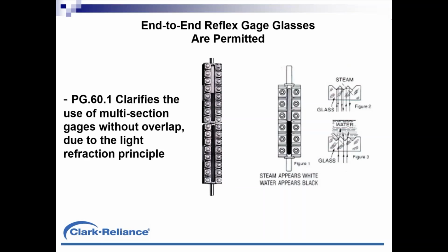So here off to the right, you can see those prisms that are molded on the inner side of the glass. So very critical, if anyone is ever servicing these gauges, the outer side of the glass is smooth. The ridges, known as prisms, must be installed on the inner side of the glass. If someone were to make a mistake and install the glass backwards, during maintenance or a rebuild, the glass would tend to look full all the time with the prism on the outside. So that would be a critical error to rebuild a gauge incorrectly.